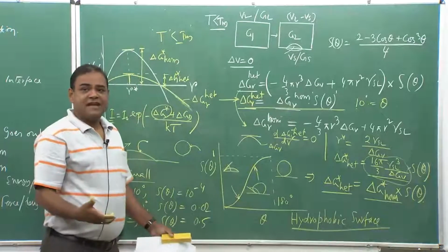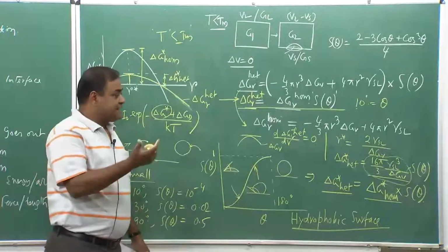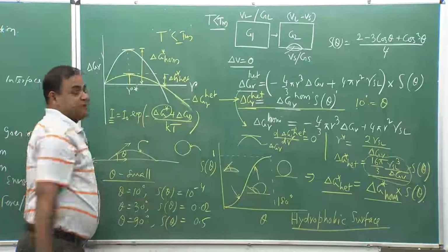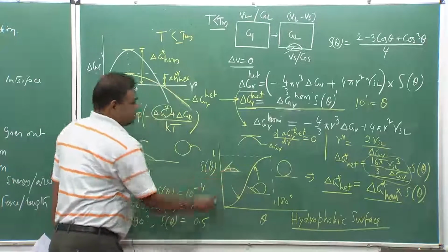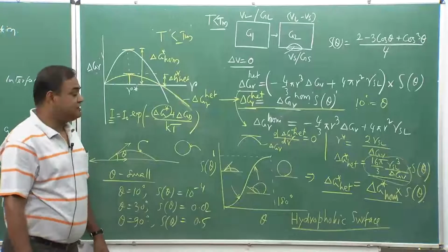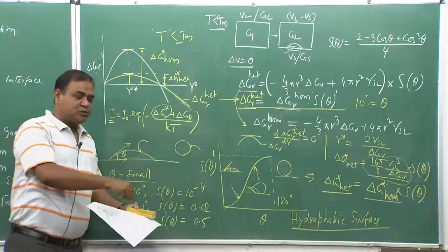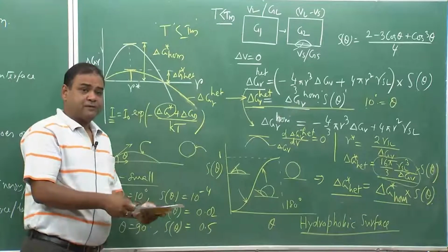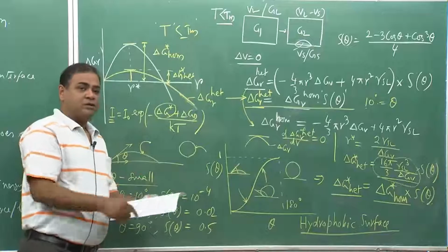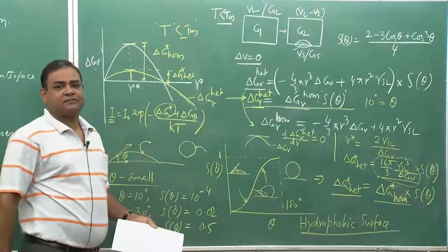So, that means everything becomes very difficult for the nucleation, because it has to cross a higher energy barrier. Now, in the case where the contact angle is small, for example, if we put water on a rough paper, we will see that the water gradually tries to wet the surface.